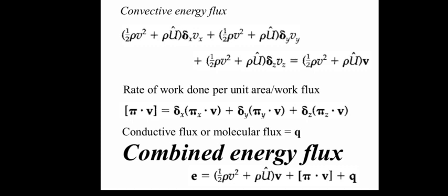One important application is the phenomenon of viscous heating. As discussed earlier, work done by viscous stresses can lead to dissipation of mechanical energy into thermal energy, effectively acting as a heat source within the fluid. It is also mentioned that the rate at which work is done is the force acting on a moving plate times its velocity. When considering the fluid between moving surfaces, the viscous dissipation becomes significant and is represented by a volume heat source term Sv, which appears naturally in the energy balance when using the combined energy flux vector.